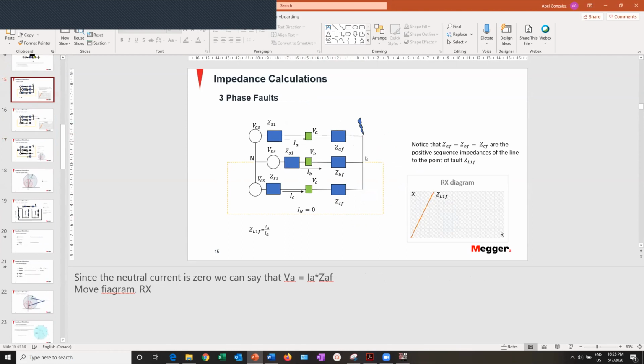The loop that you have there is made of the voltage and the impedance of the line, and you divide this voltage by this impedance and you have the current, because this point is the center point of a balanced resistance system. So by knowing the voltages of the lines, you know the voltage of the phase, and the voltage of the phase divided by the impedance of the phase gives you that current. So that would be the loop impedance for that type of fault.